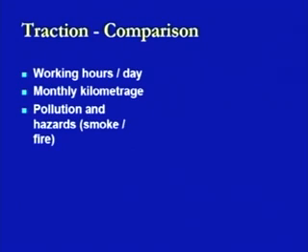Pollution and hazards: as far as fire is concerned, there is no such problem in both the cases, but there is a little smoke which comes out in the diesel engines as compared to the electrified engines. The availability for service is another aspect. Though mostly both the locomotives are available readily for use, in the case of the diesel locomotive it has to be kept in a readied condition, that is, the engines have to be switched on so that they remain warm and can be used readily, but this problem is not there in the case of electric locomotives.